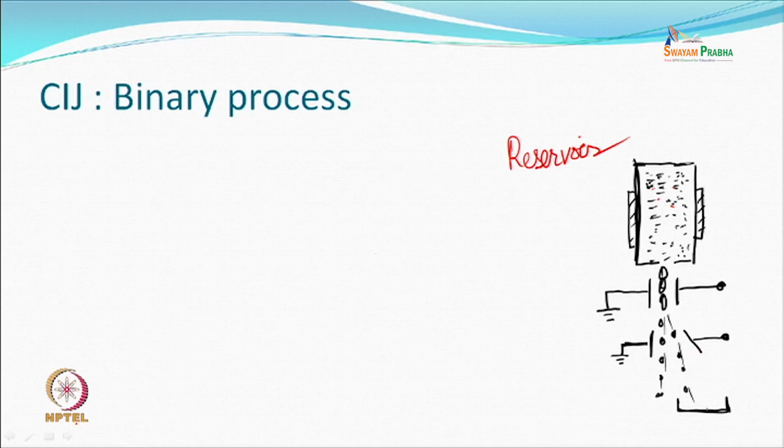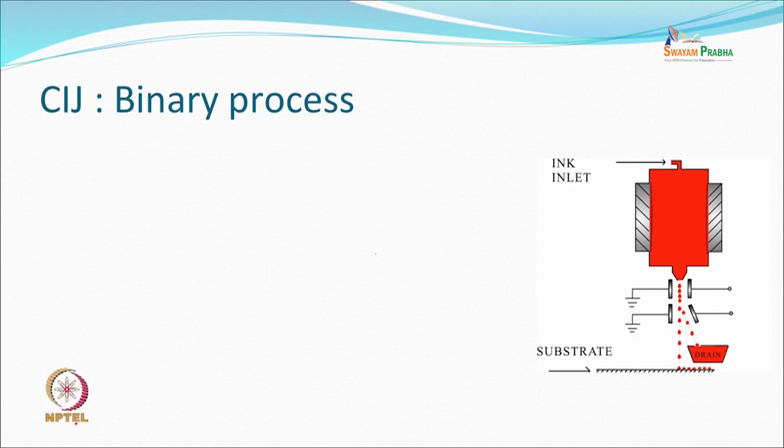So the jet is coming continuously, the head is moving obviously, the fabric may be moving in this direction, the head moves in this direction. So the drop falls. Wherever the drop is not required, it will be deflected to some other point, which can be, let's say, a drain. And wherever it is not deflected, it just keeps on falling, right? And so it reaches a point, and there must be a textile substrate where it gets deposited, and then you keep moving.